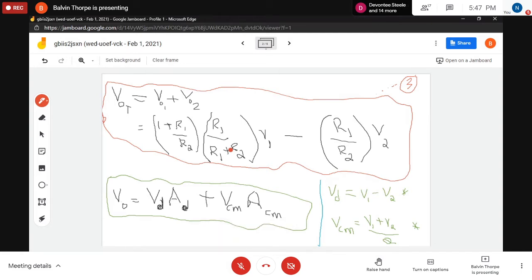So one thing that I've also said is that every operational amplifier has a general expression for output voltage. The output voltage, once you're operating as an operational amplifier, is going to be the difference between the two input voltages, which we call VD. So VD is what's going to go into the amplifier. The amplifier has a gain, which we call AD. And we know that input voltage times gain gives you output voltage.